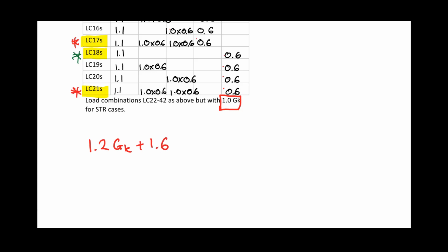If you were considering them separately, if they are correlated, that means they can act at the same time, then you could actually put them together. But when they are caused by separate things and they cannot be a maximum at the same time, we split them. But when they're correlated, then you could have them both at their maximum at the same time. But you'd have to look at physically what is causing it, and whether that is possible.